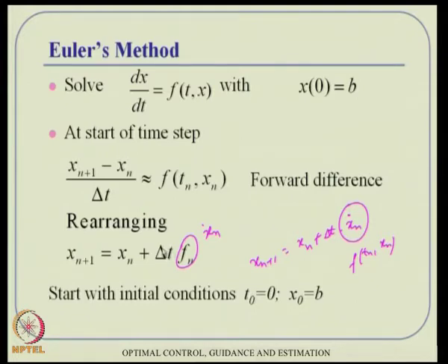And if delta t is very small, you are going to take very baby steps, which is typically not good in control theory either, because sometimes you may be caught with a trivial delta t. For example, delta t is 10 to the power minus 6, 1 microsecond, and within that 1 microsecond the control time is extremely small. In my knowledge I have never seen a control update frequency that small. Delta t being 1 microsecond, I have never seen. It's all millisecond level that I have seen. So you cannot do that if the problem demands that.